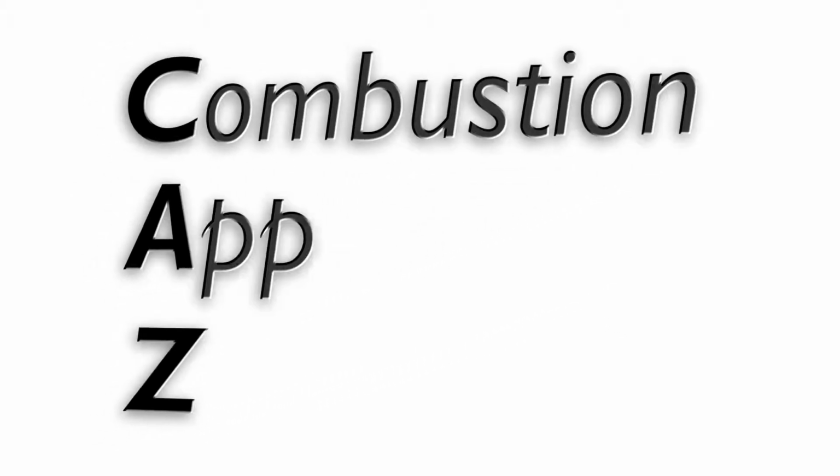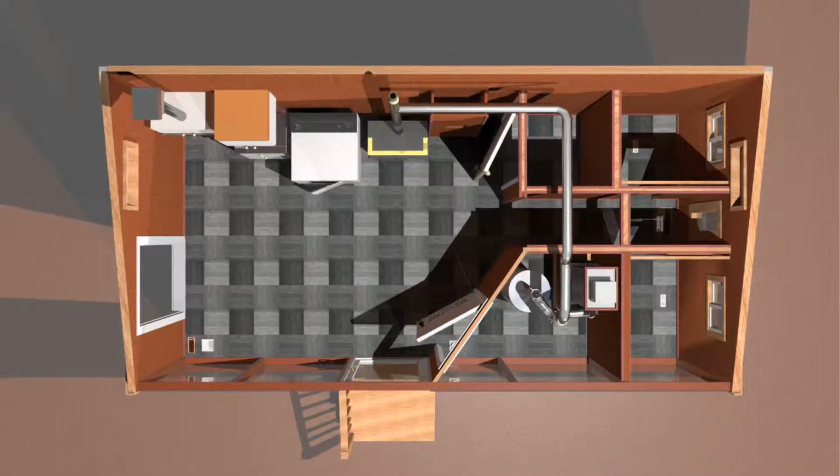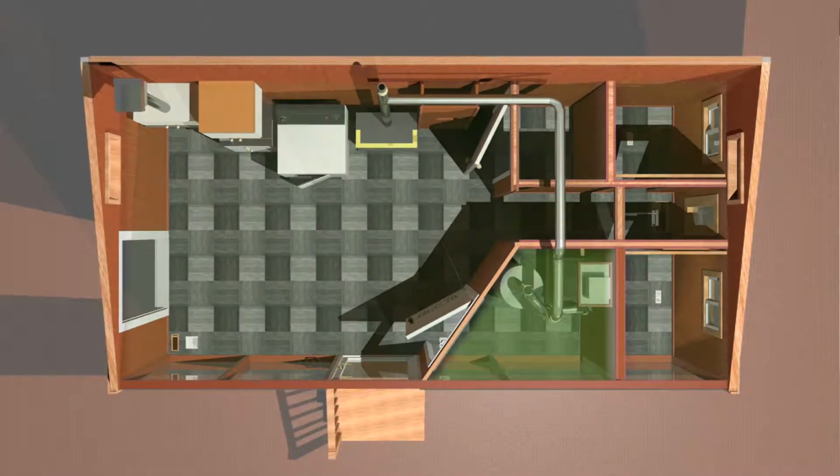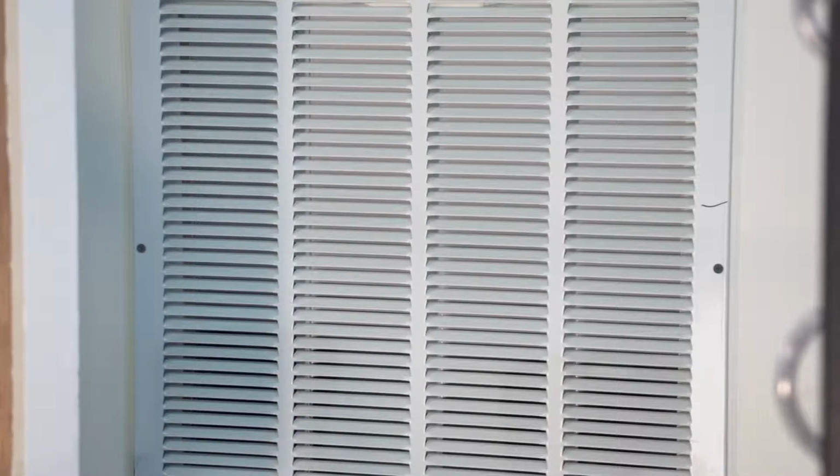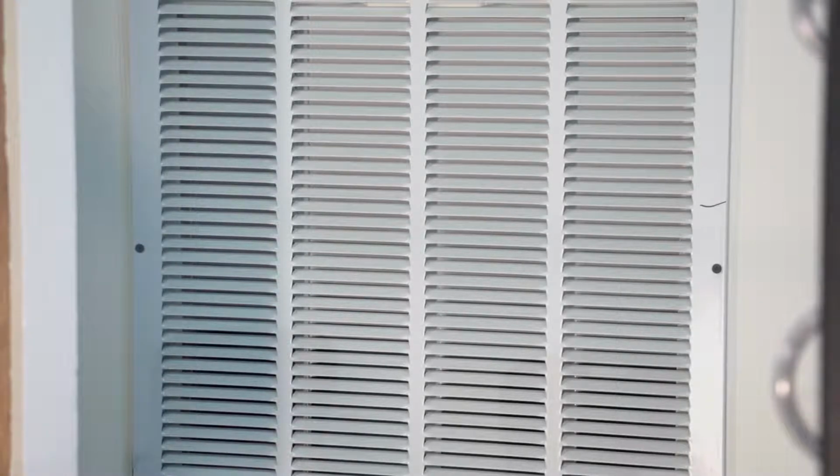We're going to learn a little bit about how we can diagnose things that are going on inside of our CAZ area. To define that for you, CAZ is an abbreviation for the Combustion Appliance Zone. This zone can be just the utility closet, or it could be the entire house. This really is going to depend on the area from which the combustion appliances, or those appliances that burn fossil fuels to produce heat or energy in some way, are in that area. Those things all need air to combust properly and to draft properly. So they're going to be pulling air from a portion of the house. In our case, we have a louvered door, so our combustion appliance zone really is the entire house.